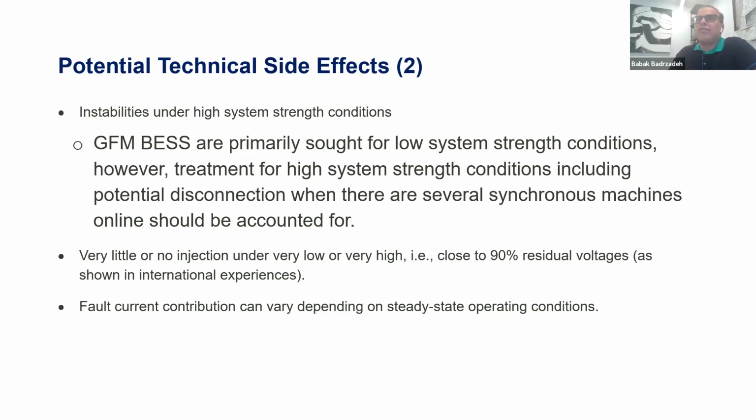So with grid forming inverters, this is not the same because they are establishing their own voltage sources. However, they don't have a mechanism for current control, or if they have it, you most likely end up in the grid following mode anyway when the current is saturated. So we're not discussing that. The subtlety we have already discussed.